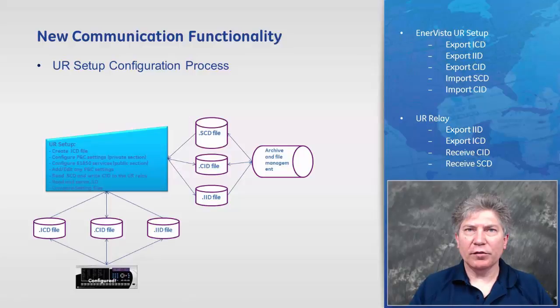From the online window of the InterVista UR Setup program, we can read the ICD and IID files from the UR relay. We can import SCD and CID files from the offline window. Each time a 61850 configuration is saved, it sends a CID file to the relay. The UR Setup program can create ICD, IID, and CID files from the offline window to be used in station configuration language tools. It still maintains the original functionality of configuring and editing PNC settings and configuring and editing 61850 services.